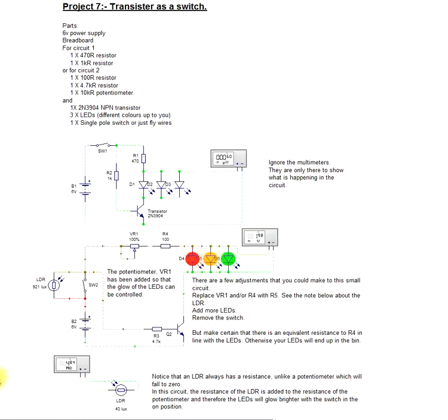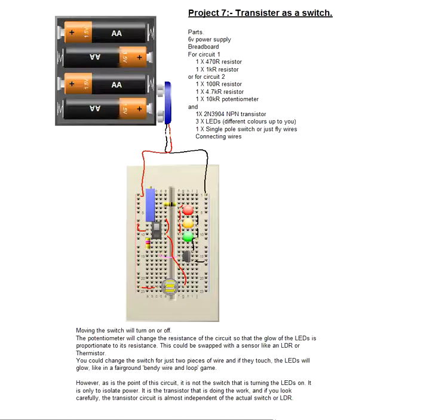Now an LDR, as you can see by this bit at the bottom, linked up to a multimeter, we can actually see its different resistance. So we're right down the bottom, we're in megohms now, but as the ambient light increases, it reduces its resistance and goes into kilo ohms and eventually down to 400 ohms, which is where we allow our LEDs to be lit in the circuits above. Quite simple, quite basic, and this is your first introduction to an external sensor, the LDR.